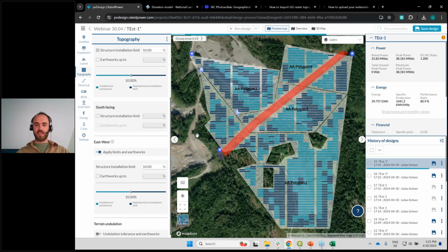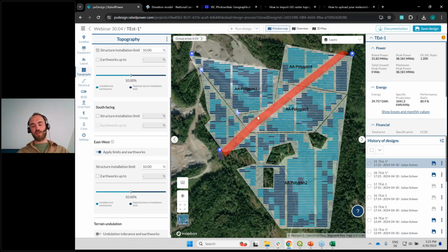So basically what we can see is two colors. The light blue is everything which is not affected. It's basically on a flat terrain which is below those 10%. And all the dark blue areas here, they are the ones which are either 10% north slope or 10% east-west slope. So the software already highlights those. And of course, by making changes to either percentage number, I can adapt it and really reflect more what I'm actually interested in. But we will just take this example today.